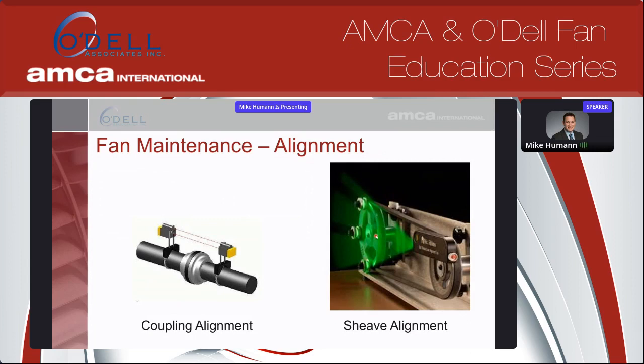Talk about fan alignment and how critical that is. You see on the left-hand side, you kind of have coupling alignment. You see typically laser aligning tools used for this. You want to make sure that you're not exceeding the manufacturer's recommendations of any angular offset or parallel offset in your coupling. So you want to make sure that's in tolerance, so you get the best life out of your coupling, but it also doesn't lead to any vibration issues in the fan or motor itself.